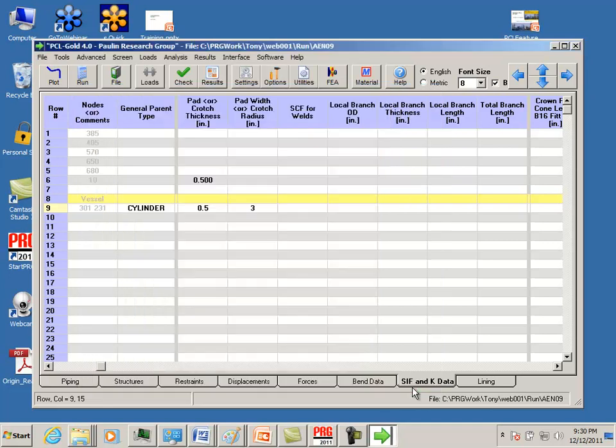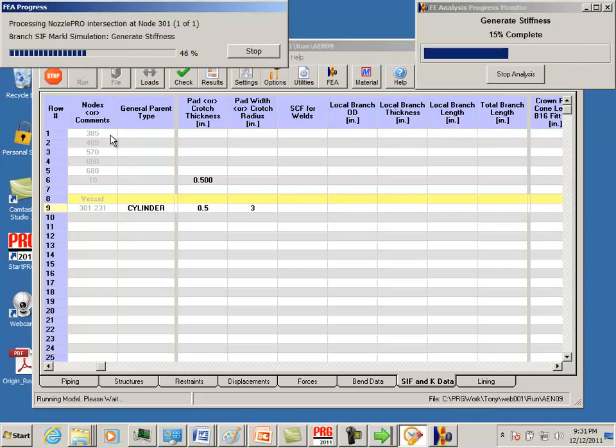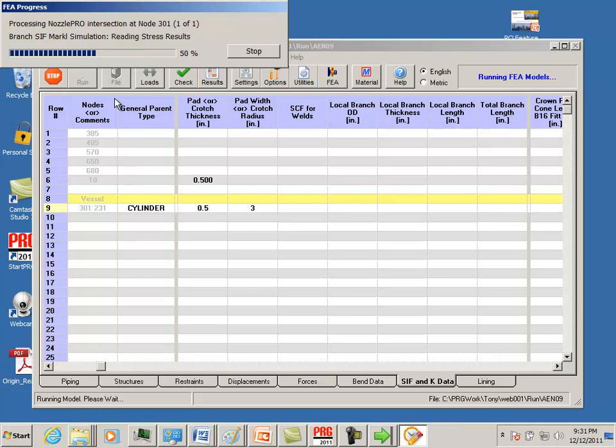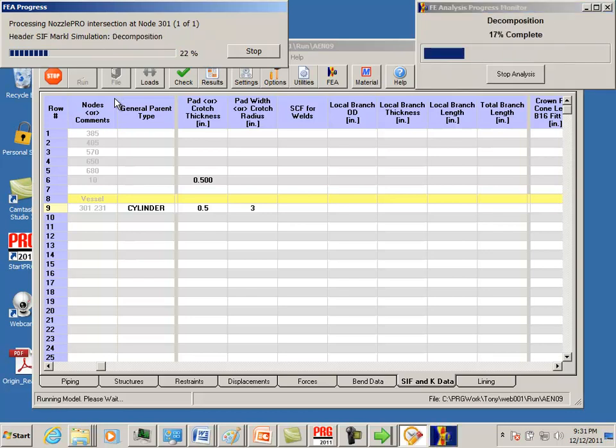So we say OK. We've entered our supports. We've entered the stress intensification factor definitions for our nozzles. We should be ready to run. The software should go out now and see that the run is different this time from the last time. We've got a request for finite element calculations. The two nozzles are identical, so it will make one calculation for each nozzle and then apply it in the place where it's needed. We'll see two calculations go by quickly here.